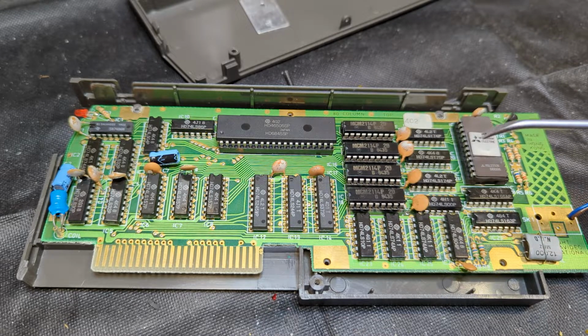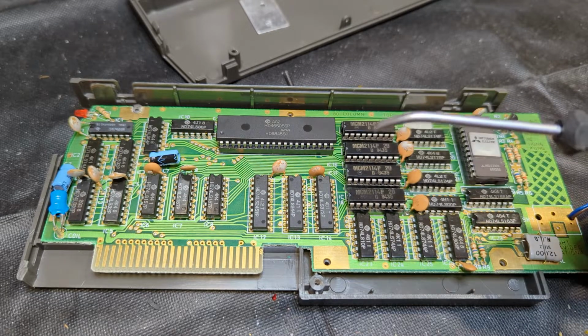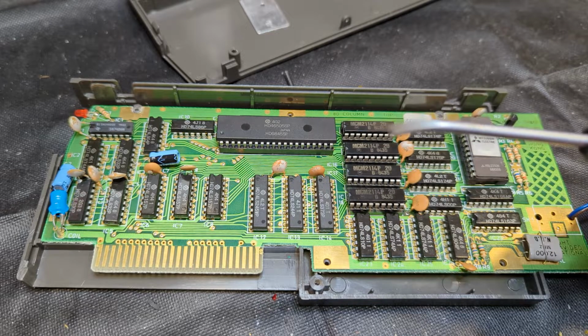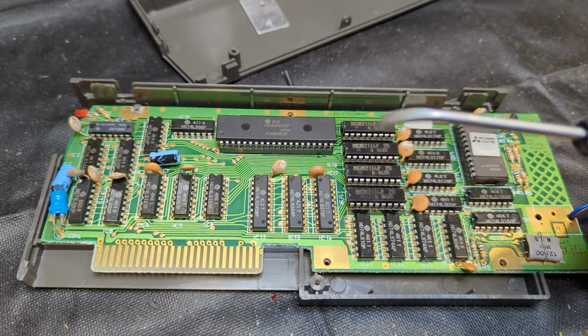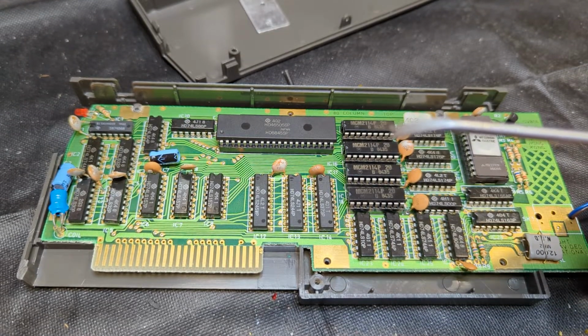Over here, we've got our character ROM. So this has got the individual bitmaps for each character, all 256 of them. And as we'll see later, there's 16 bytes per character in this ROM. Over here in the middle is the 2 kilobytes of static RAM. This is the video memory that's used by the CRTC and accessed by the main processor as well. Each one of these chips is 1 kilobit by 4, so you need 4 of them to make the 2 kilobytes.